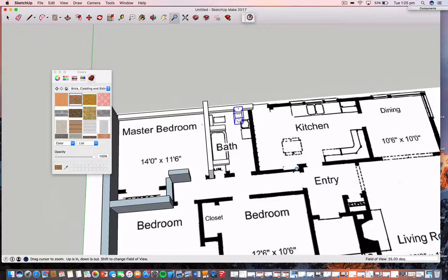The big hassle going from SketchUp into Xcode is the scale is not a one-to-one scale. So what I've found with house models is I've had to scale the model down to 0.03 of the right size, and that's been the best way to actually get it to appear a life-size model. But you might have to play with those scales in Xcode to make sure you get it to the right size. But that's quickly how you make your 3D world.